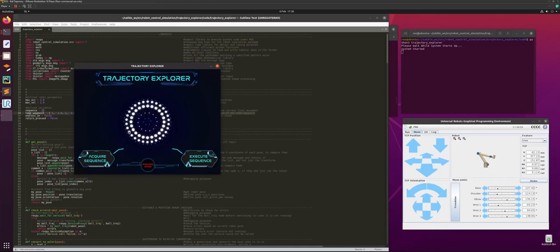That is the main reason why I decided to create my own sequence algorithm that memorizes the correct values, similar to a labyrinth solving algorithm, and then checks these sequences to make sure that certain movements do not repeat and the robot does not get stuck, and then it saves that to the file.